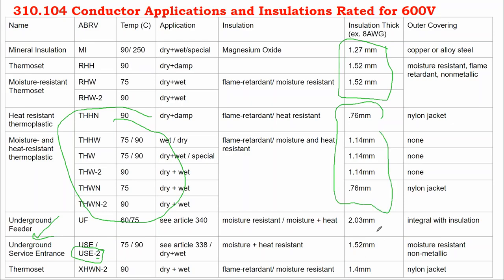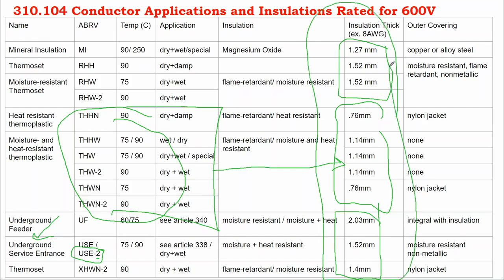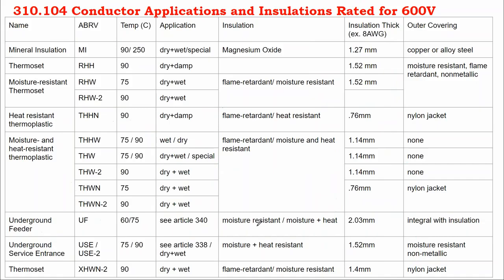Cables have different cable jacket thicknesses, which can impact how many fit into a conduit. A lot of the conduit calculators are based around THWN and THWN2 cable. Technically the amount of cables that you can fit in a conduit has to do with the area, not the actual cable. So, you can calculate conduit fill percentages without using an online calculator by finding the areas of the cables based off their exact cable jacket dimension, and that's listed in code.